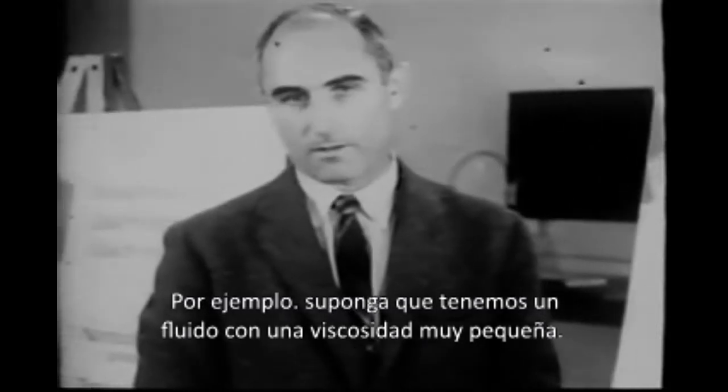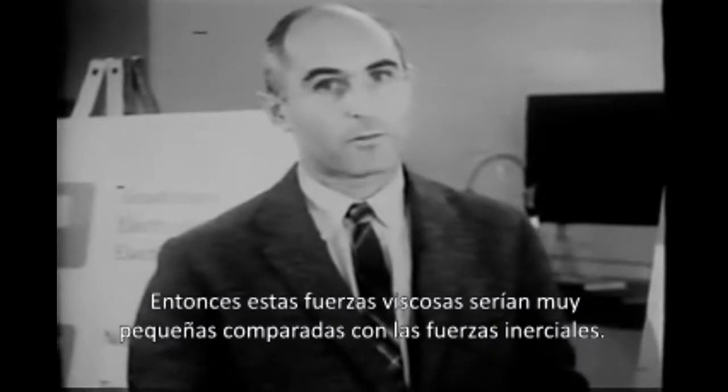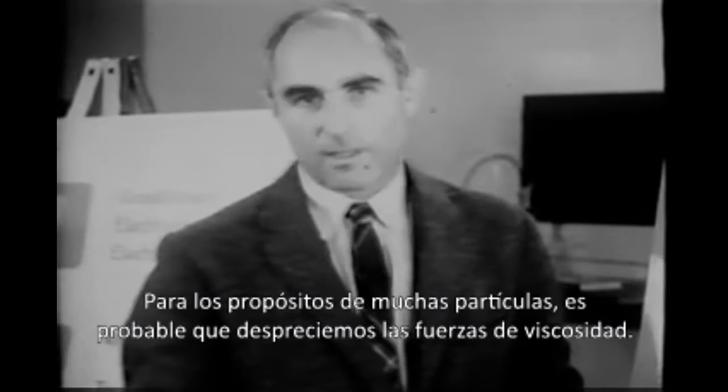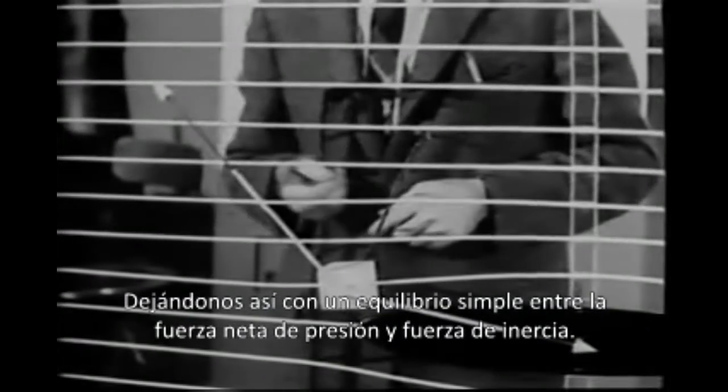The explanation of many diverse and puzzling fluid flow phenomena hinges crucially on the realization that in different experimental situations, these three quantities are of different relative importance. For example, suppose that we had a fluid of very small viscosity. Then the viscous forces would be very small compared with the inertial forces. For many practical purposes, then, we might entirely neglect the viscous forces, thus leaving us with a simple balance between the net pressure force and the inertial force.